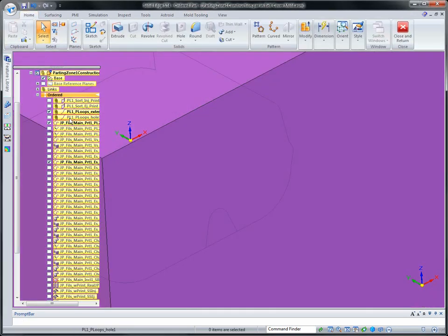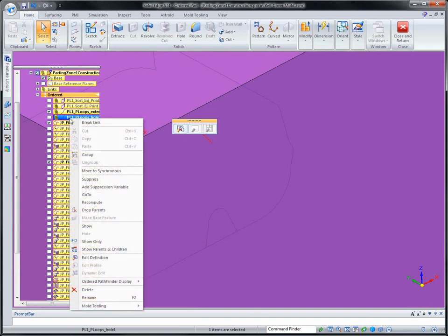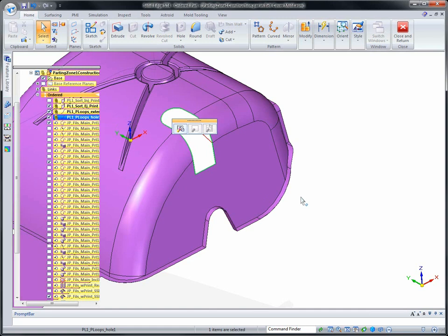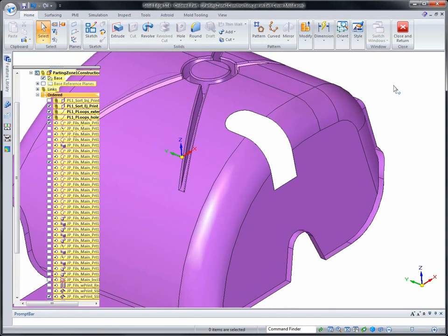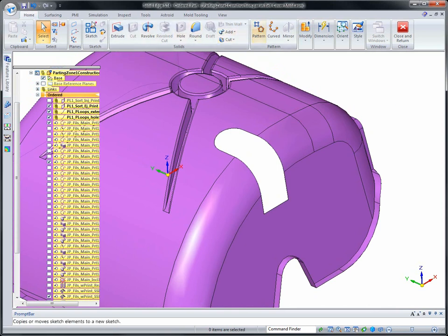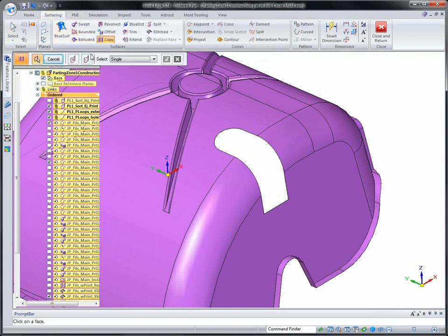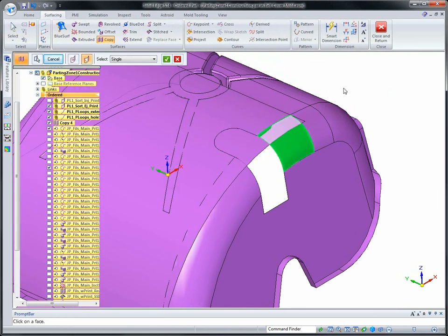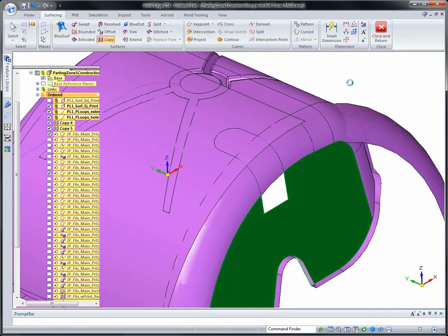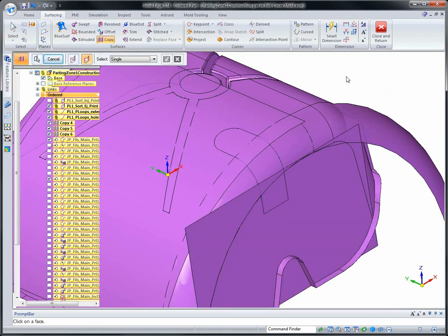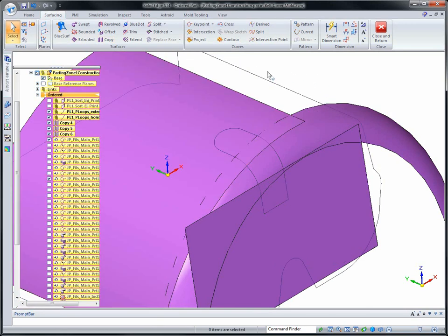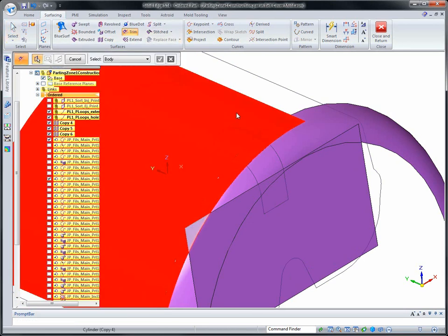So what I'm going to do is exit SEMoldTooling to where I'm just in place activated into this parting tool. I'm going to use the go to functionality. This is an ordered part, so you have the order of operations here. And what we're going to do is come in here and copy the surfaces. So I want to copy the surface and remove the exterior boundaries. When I do that, you can see you get this nice rectangular surface, or in this case the torus type surface. Basically, I copied those three surfaces and extended their boundaries so that I can come back and trim those together to make that interior face and have it match perfectly the inside of the part.